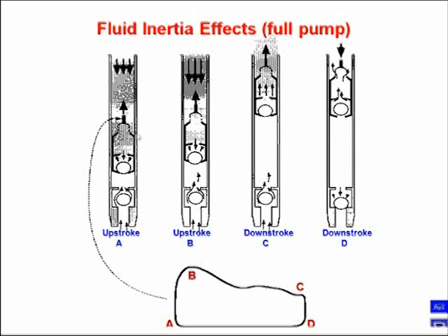Now, this is a dynamic effect. This pressure wave that we put in the fluid will move up at the speed of sound in the liquid that we're pumping. If it's mostly water, it's going to be about 5,000 feet per second, which is about a third slower than the speed of sound in steel.